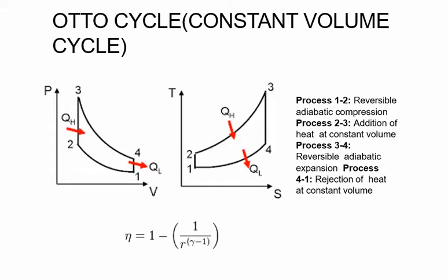The Otto cycle is a description of what happens to a mass of gas as it is subjected to changes of pressure, temperature, volume, addition of heat and removal of heat. The mass of gas that is subjected to those changes is called the system. The system in this case is defined to be the fluid, that is the gas within the cylinder. By describing the changes that take place within the system, the system's effect on the environment is also described.